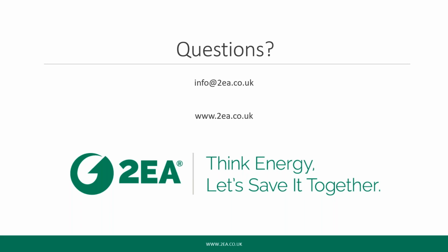Thanks, Andrew. And the next question is, are there some instances where electrically led CHP units are more efficient? I wouldn't say they were more efficient. I think there are opportunities out there for electrically led CHPs. I think it's driven by the cost, by the spark spread for the customer. But yes, I've looked at installations where electric only generation does actually work. In some ways, it goes against the principle of CHP and saving emissions and reducing carbon, but it is possible, yes. What you have to be careful about is that you must have some heat usage. Otherwise, if you're just purely electricity and no heat, then it is unlikely that the CHP QA would class that as a CHP unit, especially if you've got zero heat, because effectively you're just using it as a generator.